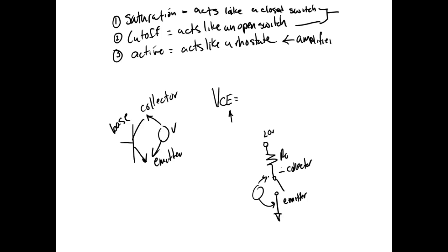Okay, so I've got 20 volts up here, and common right here. How much voltage is RC dropping? It's going to measure 20 volts. That's exactly right. So is that open, or is that saturated or cutoff? If cutoff, VCE is going to equal VCC, the collector voltage. Okay, so let's close the switch. Now what would my meter measure?